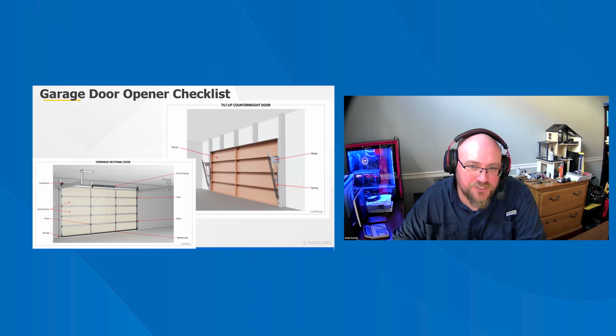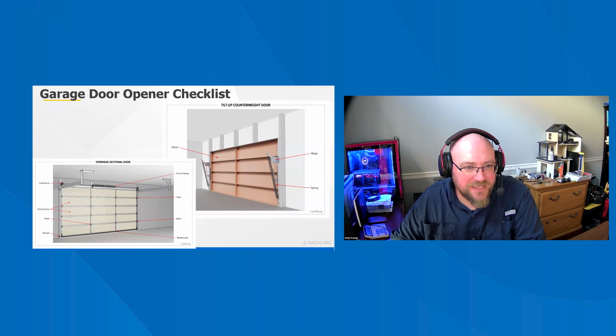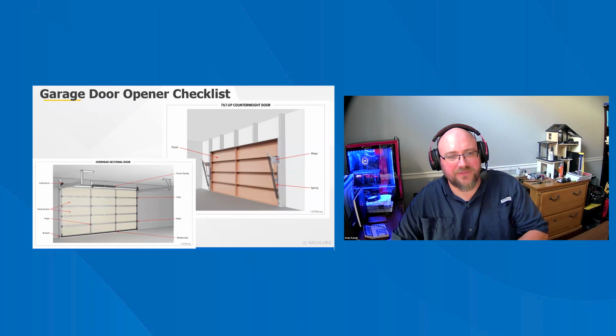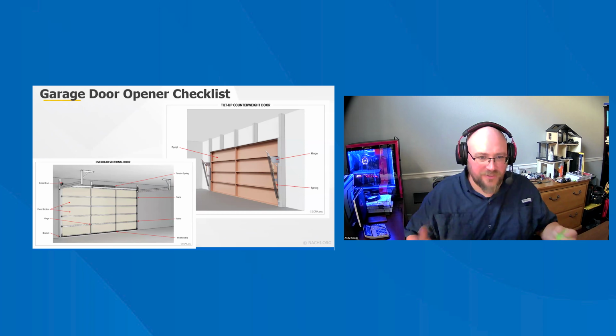Me personally, I no longer check the automatic reverse on a door. We've had too many upset clients, realtors, or whatever. We do put a comment in our report that recommends testing the door monthly and recommend contacting the manufacturer for testing recommendations. But we personally do not test garage doors anymore. Too many have broken. There's been too much fight back and forth between realtors, sellers, and whatnot. We will operate the door with the button, and that is it. And make clear observations if there's any damage or anything not installed correctly.